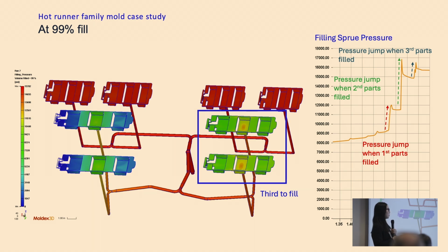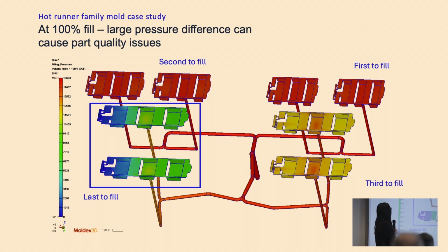potential part quality issue, but this also means that energy requirements will be larger for these kinds of increasing injection pressure, required because of increasing clamping force required too. And finally, in the end, the largest parts are filled, but you can see from the pressure results, there's a large difference between all the different part sizes.